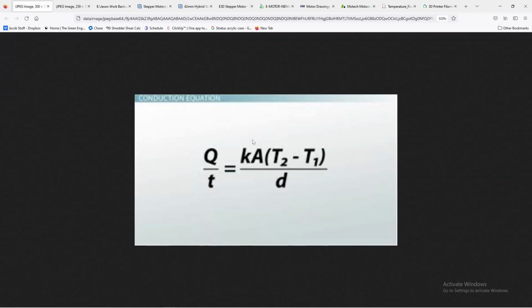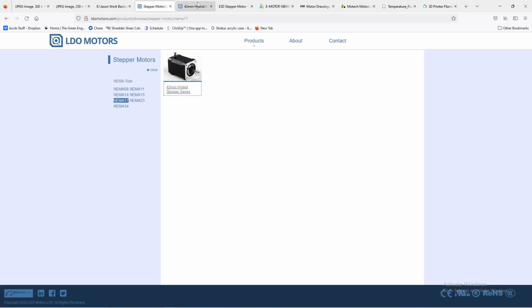K, right? And then also how much contact area or surface area of the material you have, how long the stepper motors are, the airflow that you have inside the system, and then if you have any passive cooling options: heat sink, active air, water cooling, etc. Or you have a special stepper driver where you are modifying the stepper driver settings, right?